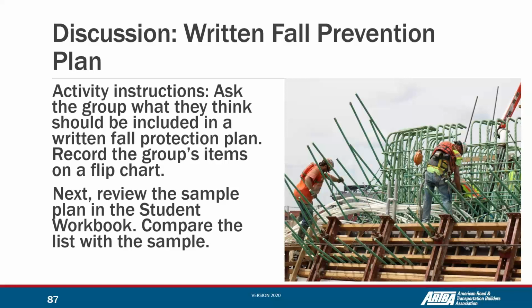Then the engineering control: how are we going to design the work zone in a way in which we can prevent falls? Then we have the administrative control. It's about training. What training are we going to provide to our workers? Are we going to rotate people, or are we going to create some restricted areas in which only allowed personnel or trained personnel can go to this place, and so on. Some rules that we can create with our workers.